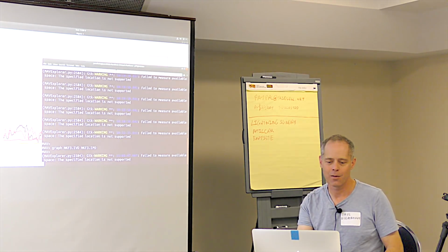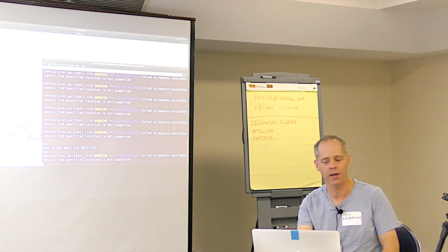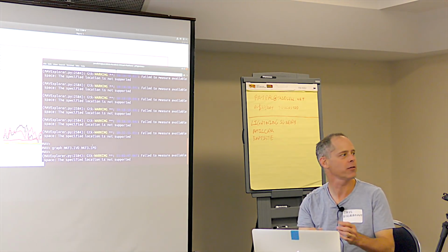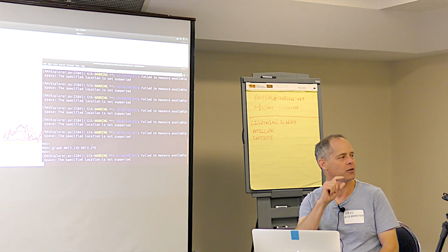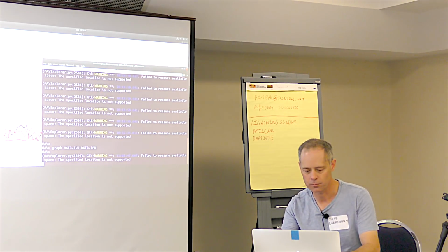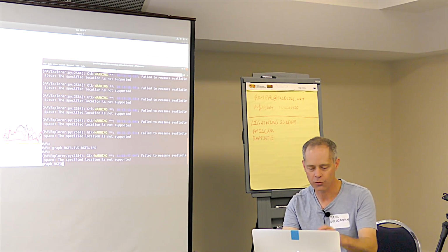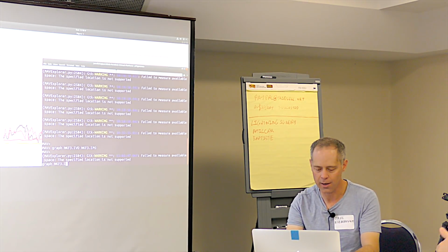So the first step here is, is this a GPS glitch or is this something else? Let's have a look at the innovations for everything that contributes to the vertical velocity measurement of the vehicle. So we graph EKF3.IVD.